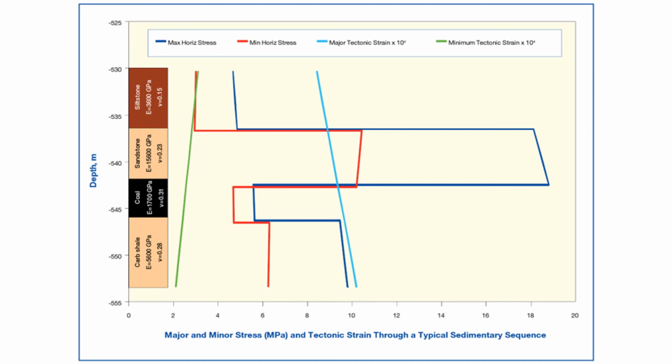Interpretation of rock stresses. Most stress measurements are point measurements within a borehole. What is needed is some means to interpolate the stress situation between these points of measurement. Where borehole breakout exists, it provides an index of rock stress over rock strength over a length of the hole. Core ovality may also be used to determine the difference in rock stress over the length of the hole. It has the advantage that it does not require the rock to break out.